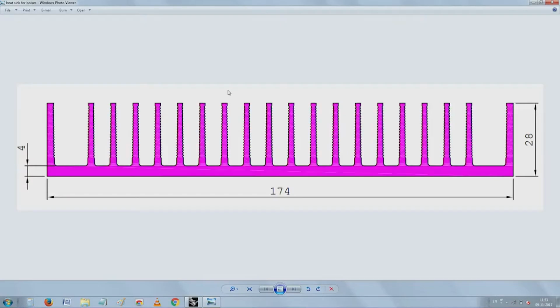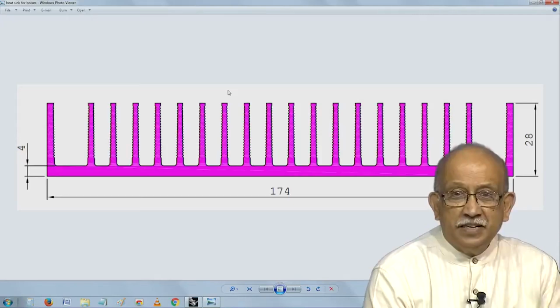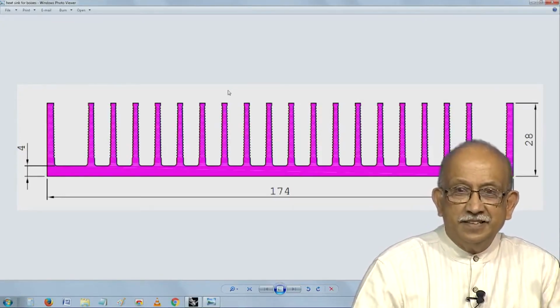I will start with having estimated the loss in your equipment, meaning if it is maybe a 10 kilowatt device, and you expect steady state losses at the appropriate loads which we know. Partial load is very inefficient, overload is inefficient, at the correct load the efficiency will be optimal, and probably the best efficiency you can get is about 90%. So, 10% losses will be there.